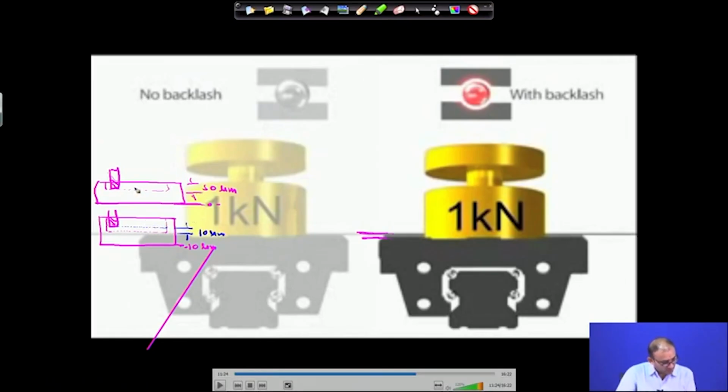Your depth of cut required is 50 micron, so this is required, but what you are getting is 40 micron, correct. So, 10 micron is moved down because of this backlash. It is very difficult to realize this during machining, but ultimately when you complete the machining and measure the dimension, only then will you find that there is an error. So, it is better to avoid the backlash.